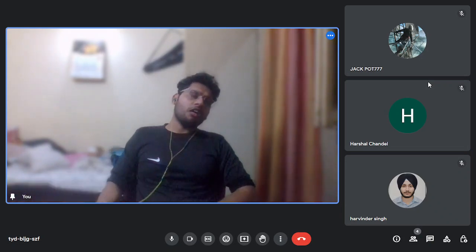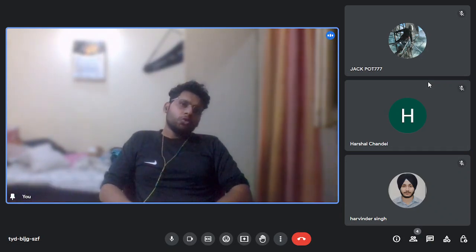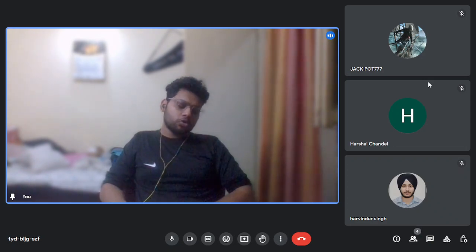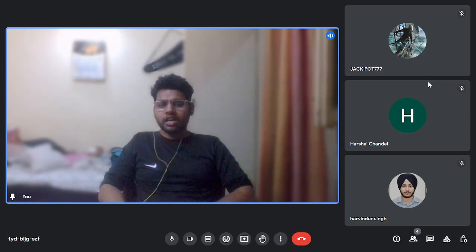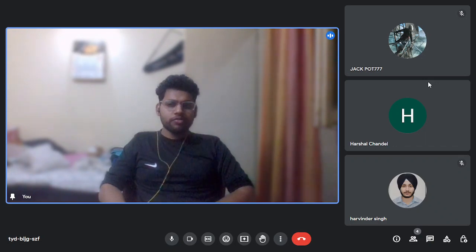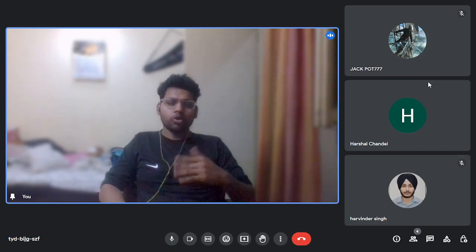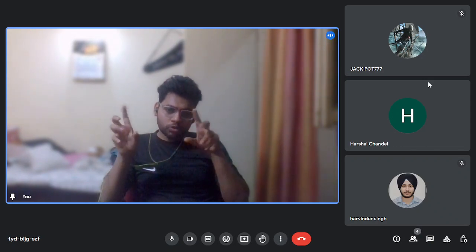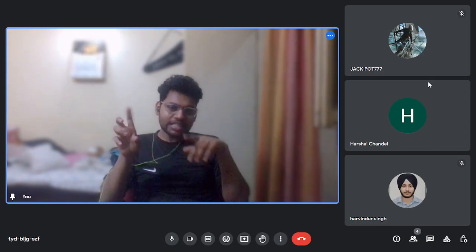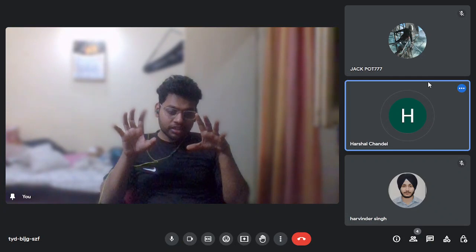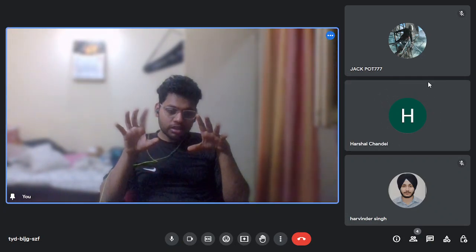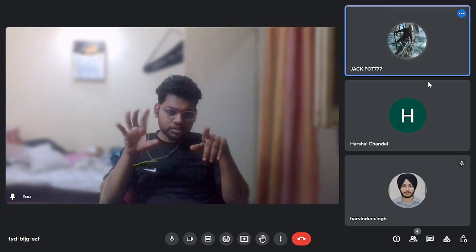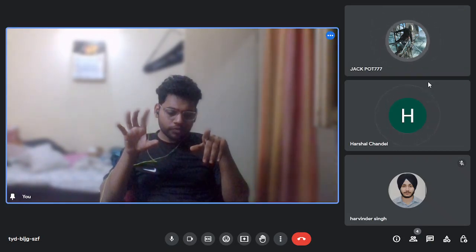Harshal, why do we use gear arrangement in a case of four stroke? There was one reason I have heard, and I need some clarification by Jack. Since the camshaft and crankshaft don't revolve at the same speed, gear is something that is used when there is a speed difference.